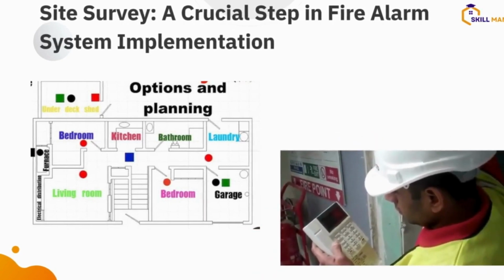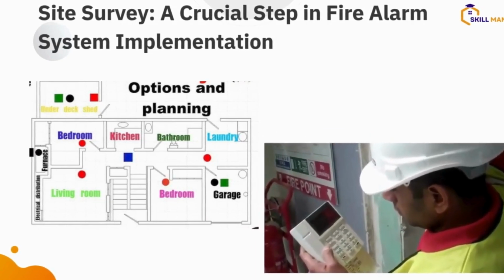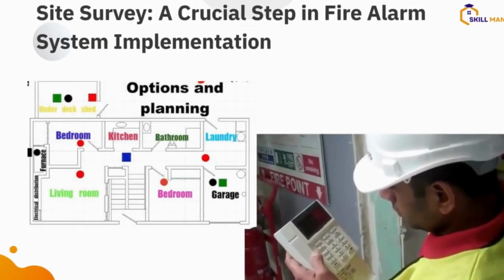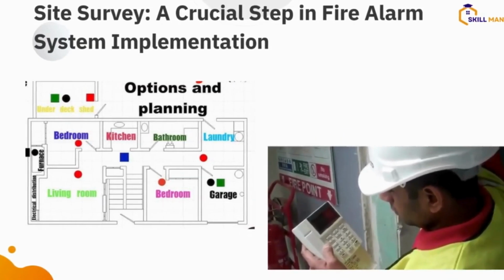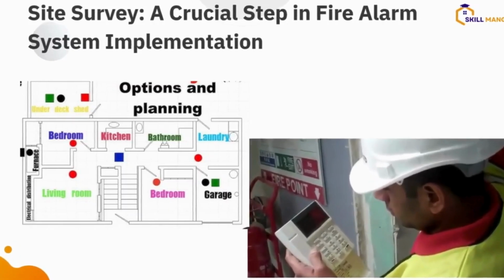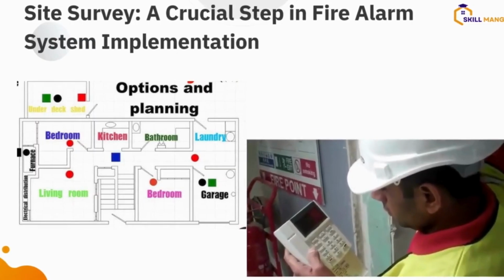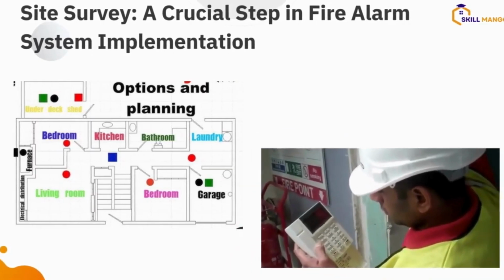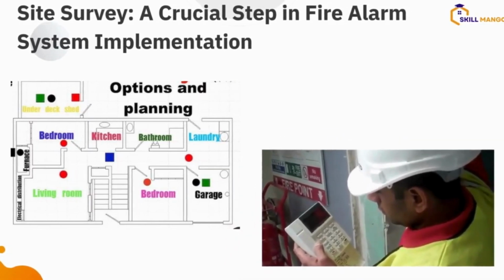You have to tell him everything, and the cable ends at the control room, which is the point where you're mounting your panel. So you have to communicate clearly with your electricians at this stage. It's very important because that's the major part of the whole project, the cabling, the routing.